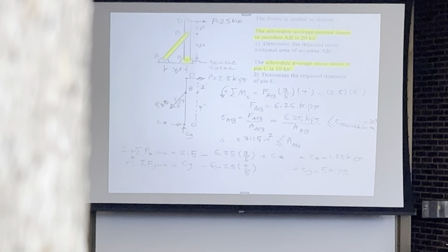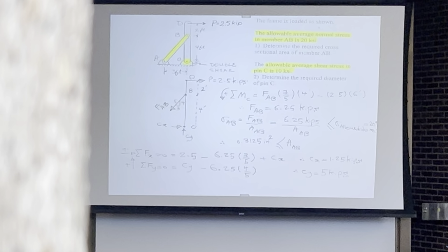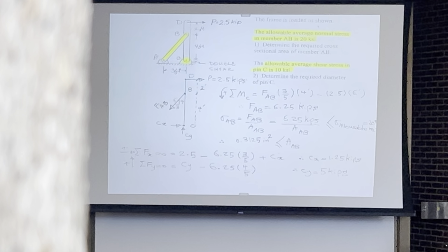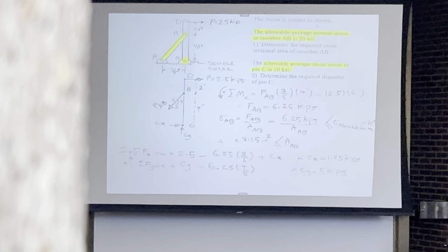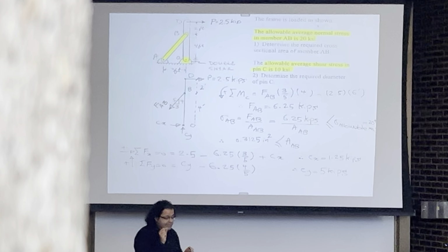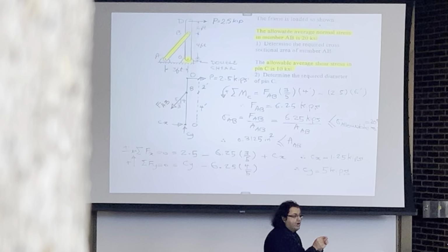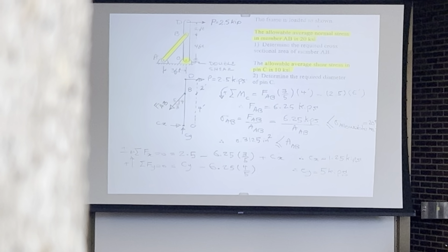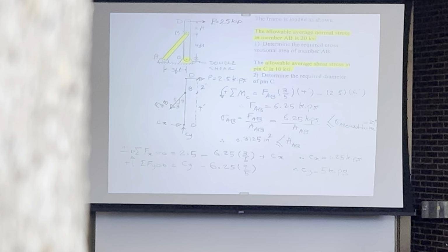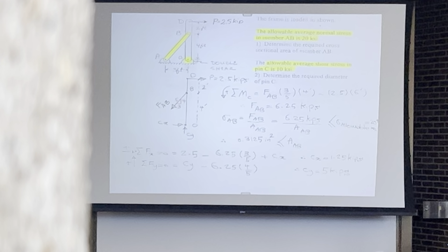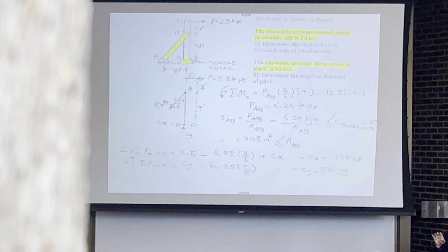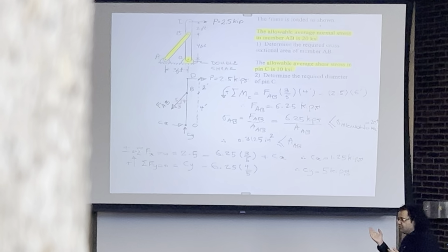We can divide those values of stresses, those limits, by a factor of safety and get access to a valuable quantity that we call the allowable stress. And an allowable stress is a material property. So if we do have an allowable stress for the material that has been used in the prismatic bar and bolt, we can actually design them. We can find the most optimal cross-section, the lightest cross-section, the least amount of cross-section that can be used for such a metal.